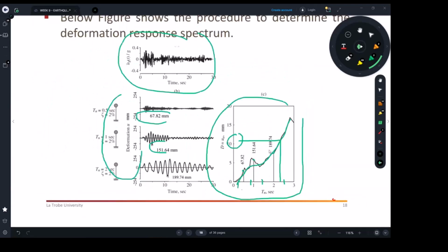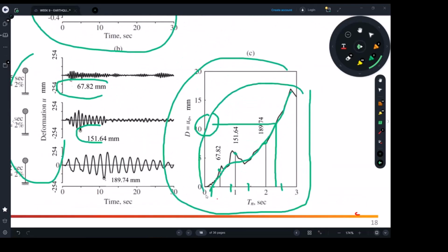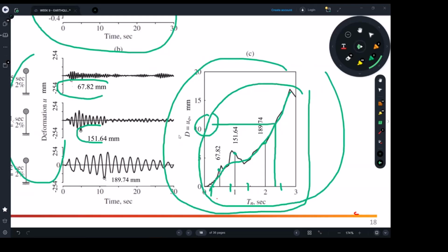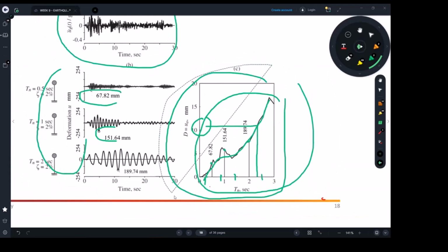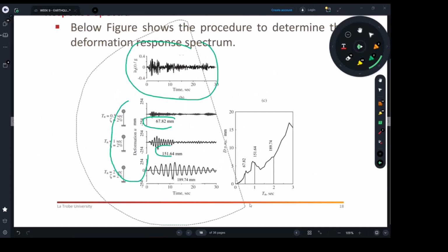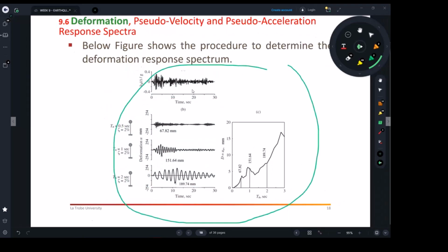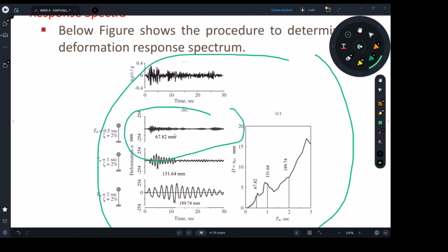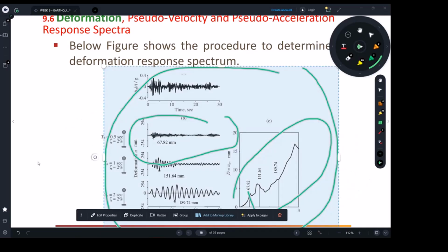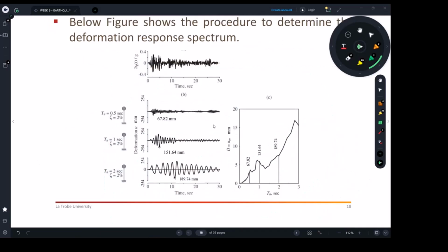Here we just took you through the process of developing your own displacement response spectra, and similarly you can do velocity response spectra, same thing, and acceleration response spectrum. That's really the story behind it. We start from what you developed last week, you repeat it multiple times, then you work out the spectral curves that you will be asked to use to design a particular structure or building.